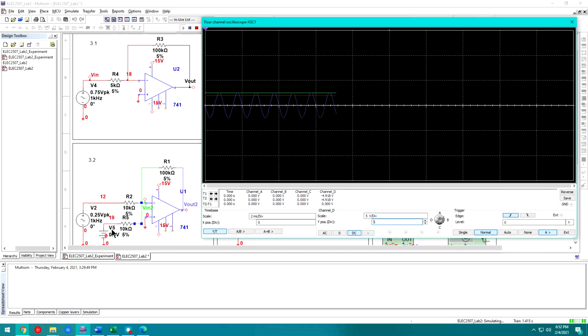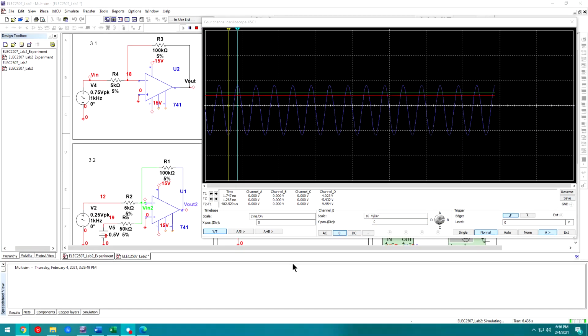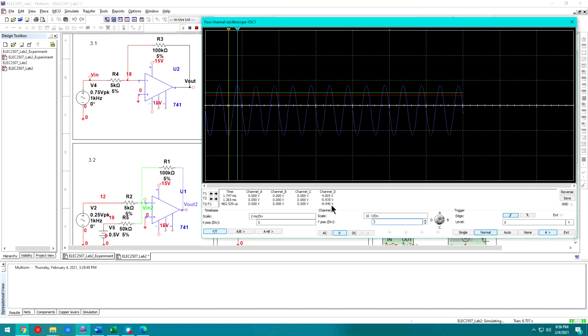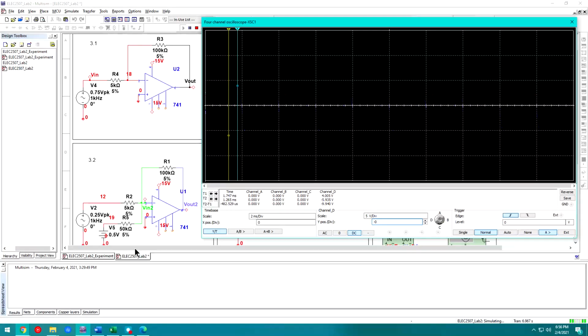And that makes sense, right? Because I have 0.5 volts going in here. So we can see the gain is virtually the exact same as the inverting op amp, right? 9 volts, and I'm putting in the exact same input. But the DC level is the only thing that's shifted here, and that's due to this DC input here. So you can go ahead and draw that in your lab book of what would happen when the 0.5 volts input gets amplified by whatever combination of resistors you have here.